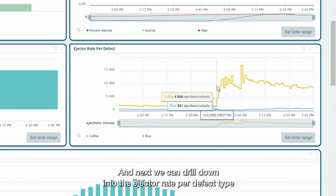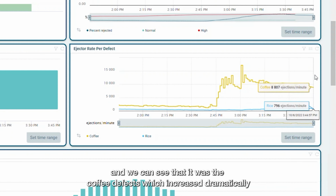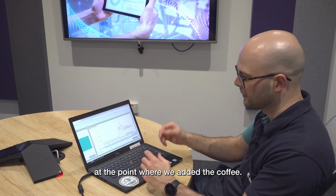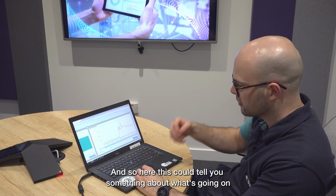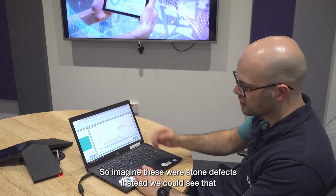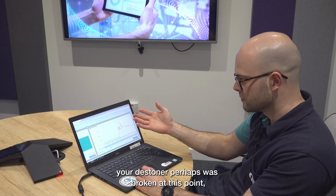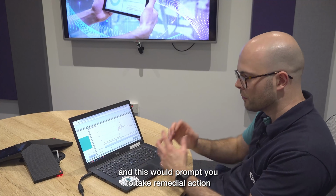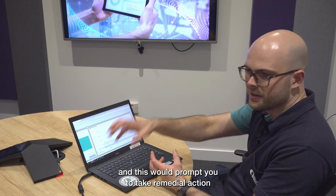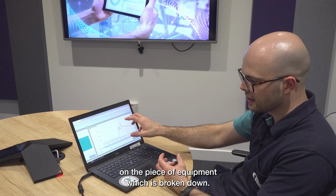And next, we can drill down into the ejector rates per defect type, and we can see that it was the coffee defect which increased dramatically at the point where we added the coffee. And so here, this could tell you something about what's going on upstream of the process line. So imagine these were stone defects instead. We could see that your destoner perhaps was broken at this point, and this would prompt you to take remedial action on the piece of equipment which had broken down.